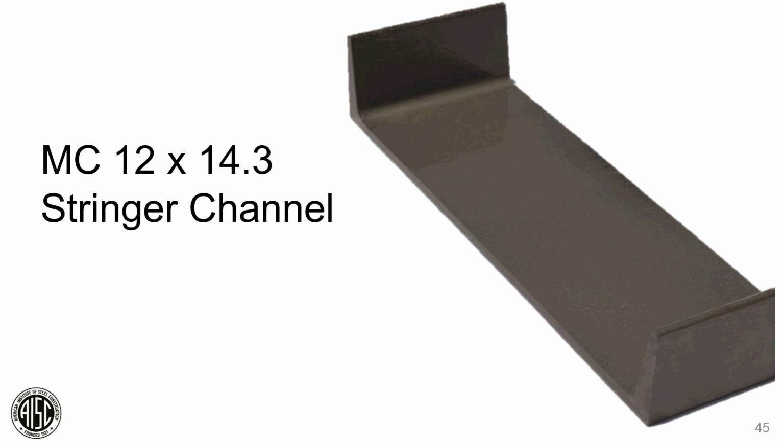The only other shape that possibly would work for that application is a C12 by 20.7. And again, this would be a case about over-specifying material. If you specify a C12 by 20.7, it's going to work. It's going to have a wide enough flange for you to make it work. But you're actually buying more material than what you need. If you specify an MC12 by 14.3, it'll be less expensive. I'm going to caution you as well, though, please check with your fabricator before specifying it to make sure it is available in your area.